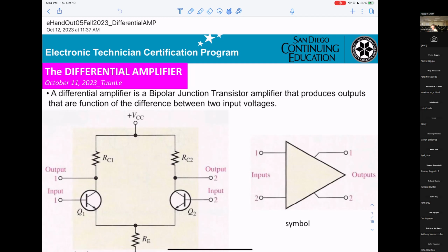And the resistor capacitor at the emitter, that will be the bypass capacitor. Okay. Without the bypass capacitor, the gain will not be big. Okay. If you want more gain for the amplifier, that's why they need the bypass capacitor.